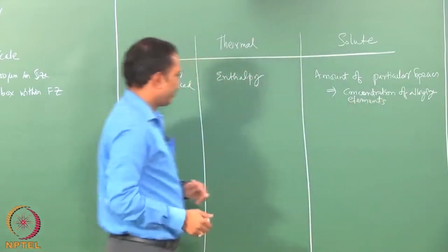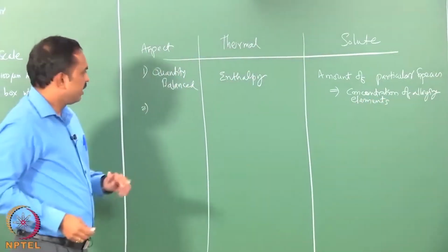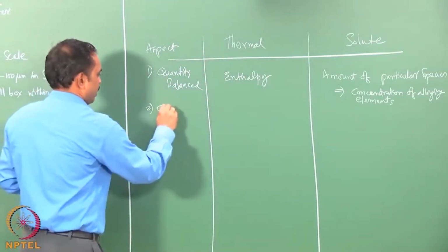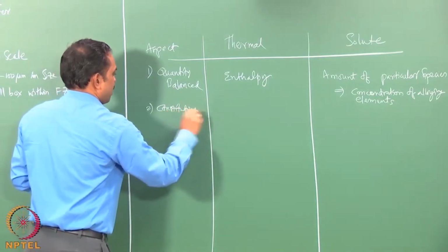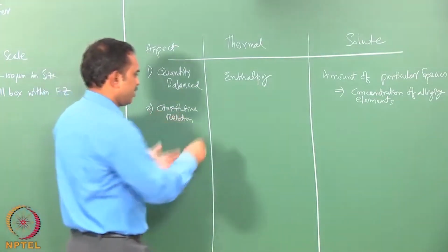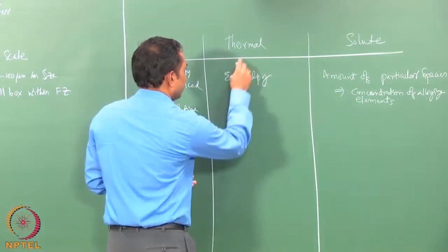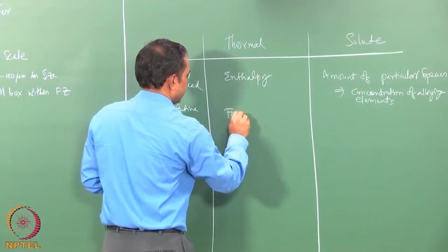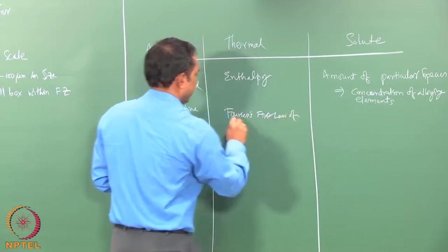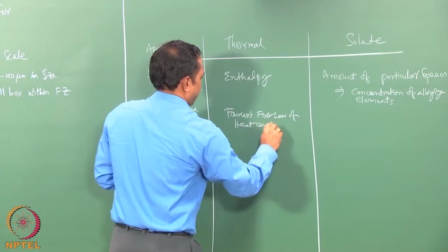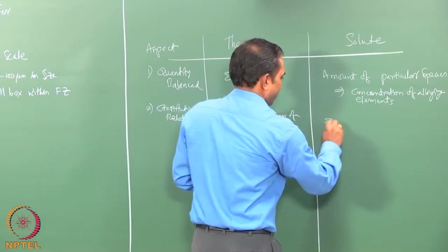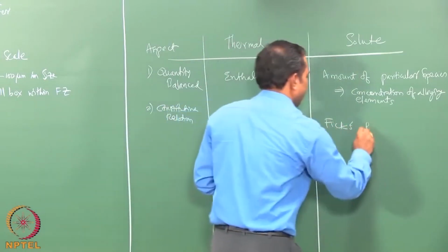you can say like that, because for most of the metallic materials the analogy is adequate with just the elements. Okay. And in the thermal model we have come across what is called a constitutive relationship, and that is basically governing the cause and effect, and in our thermal model we said that it is the Fourier's first law of heat conduction, and in the case of solute transfer it would be Fick's first law.